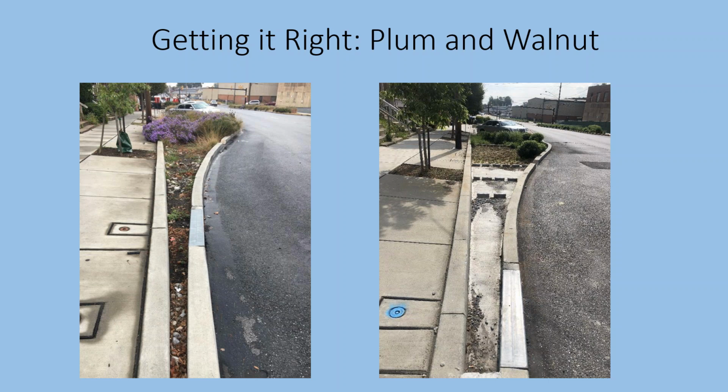This is coming down at a pretty significant slope, so we wanted to make sure we had adequate settling time as well as velocity dissipation. And even though it's very early in the growing season, you can see that this one is doing much better despite having a lot of the surface area covered with concrete. Next slide.